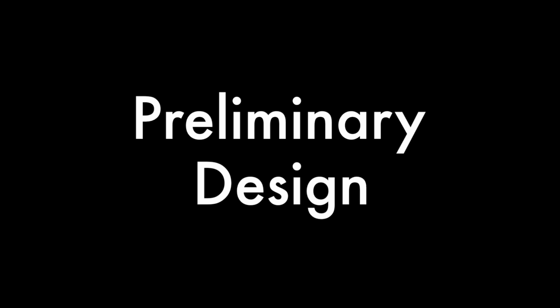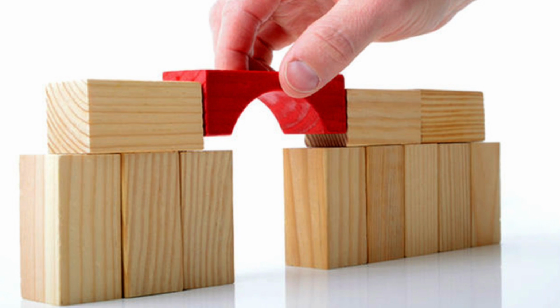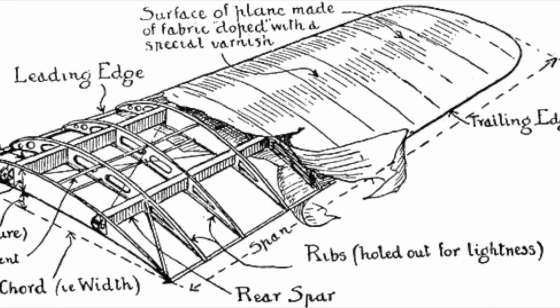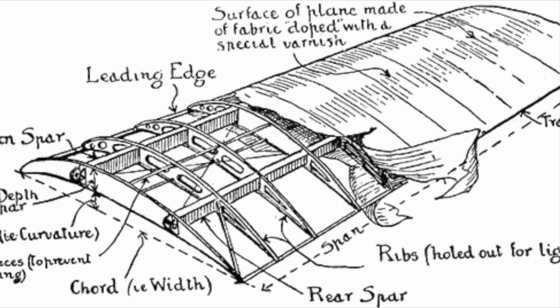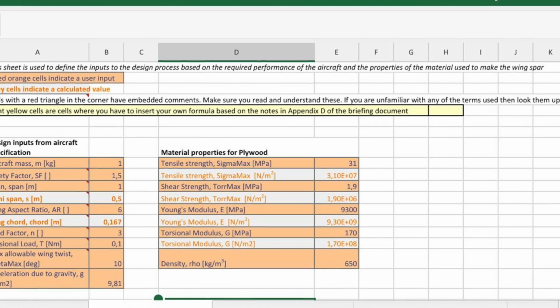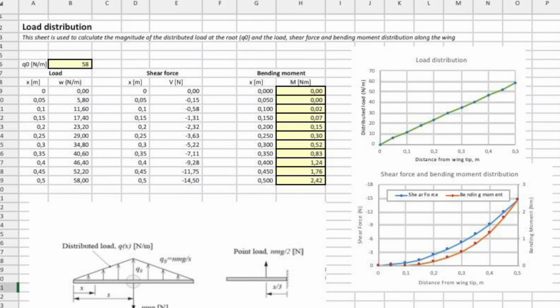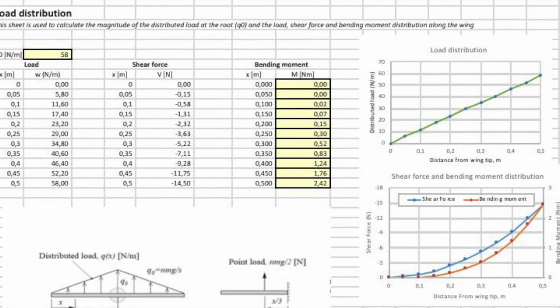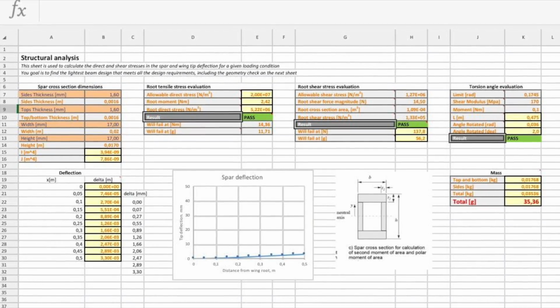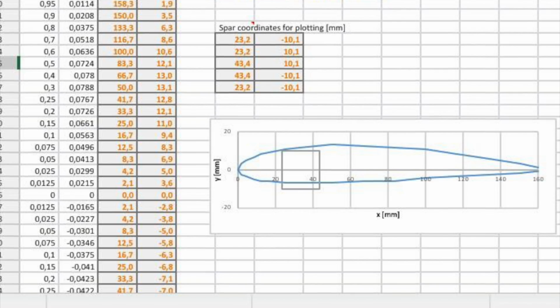And then we have the preliminary design. The preliminary design often fills the gap between design conception and detailed design. Thus, in this task, the overall configuration of the system is defined and the schematics, diagrams, and layouts of the project can provide an initial configuration of the project. For this step, we used a spreadsheet through Excel that allowed us to try several options. The goal is to achieve a set of performance requirements while minimizing different costs, such as the weight.